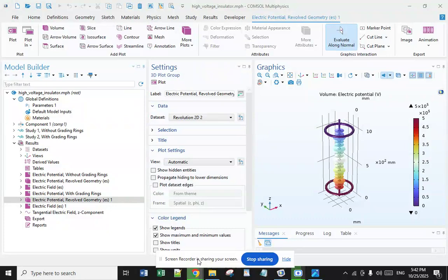The next one is epoxy resin insulators. Epoxy resin insulators are another type of low voltage insulators. This consists of an epoxy resin body attached to a metal base. The advantage of epoxy resin insulators is their high resistance to corrosion and the effect of sun and wind. They have high mechanical strength and are lighter than glass or porcelain insulators.